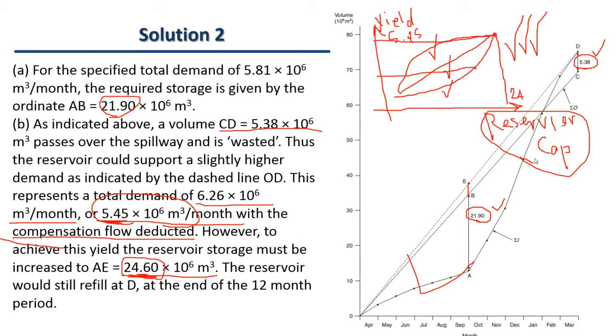The point is not only for the purpose of taking 100% of the water. In some cases, if someone is just trying to take advantage of the water, maybe it's wrong. They say, let's not have any flood, because they want to use 100% of the water for yield, for, let's say, irrigation, industrial purposes, whatever, or domestic use, and they are only obliged or committed to release the compensation flow. And that is not true.